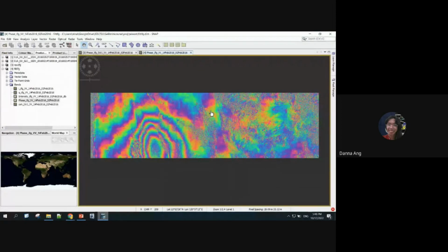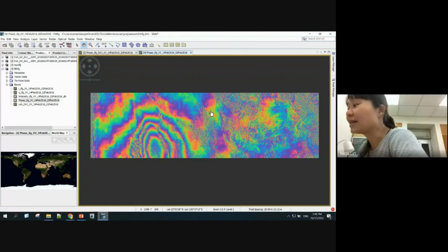Hello. Hi, Dana. So, I think you do phase unwrapping because when you only have the phase, you don't know exactly what the elevation is, because your phase is a number that repeats. So you unwrap to retrieve the original elevation data. Yes, thank you. Yes, that's correct.